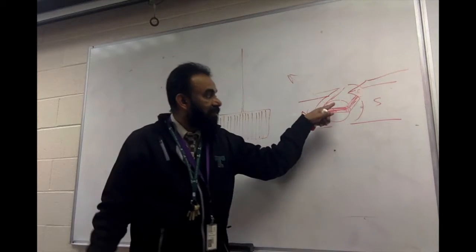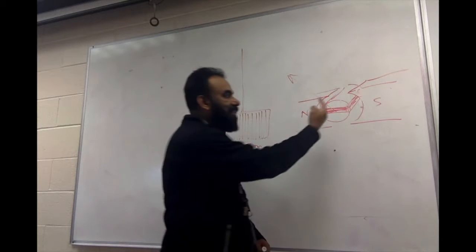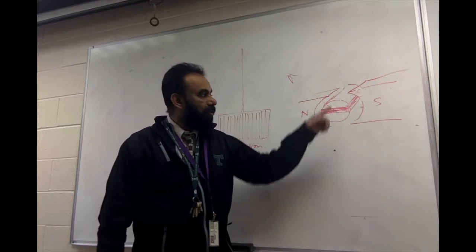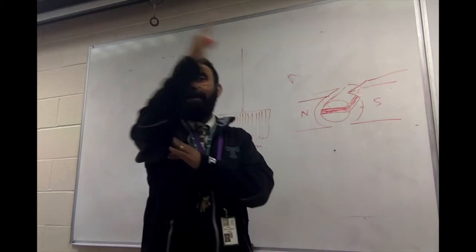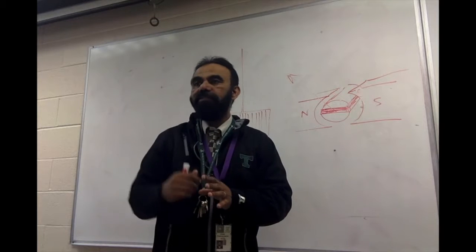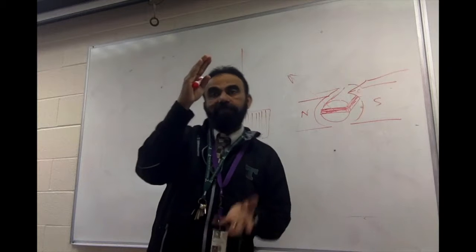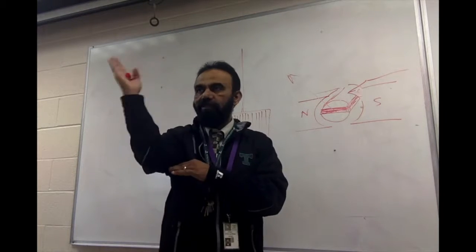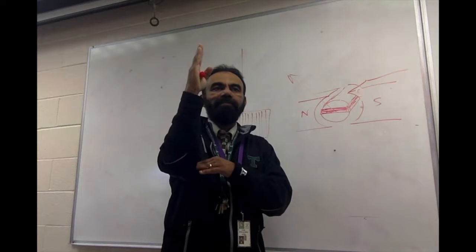Is because this core, when the core moves in the magnetic field, what is being set up in the core? Eddy current. So eddy currents inside here flow in such a direction to oppose the cause. So if the pointer is trying to go that way, the eddy currents are trying to prevent its movement. And if it swings too far, then it is going to come back, and when it comes back, opposition. So opposition all the time is what suppresses the oscillations like that. See? When you connect it, it goes like, that's it, over.